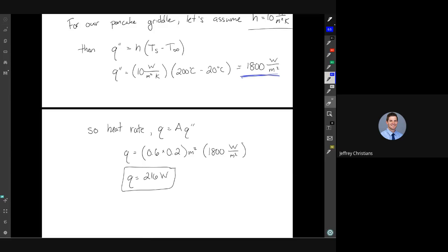So a temperature difference in Celsius and a temperature difference in Kelvin are equivalent, because it's a delta T. But my general rule is if you're doing things in Celsius, you sometimes can be wrong. If you're doing things in Kelvin, you're almost never wrong. So when in doubt, flip things to Kelvin, even if it takes 2 extra button pushes on your calculator to add 273. If you're unsure, I would just do it in absolute temperature.